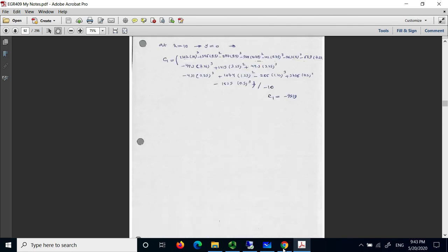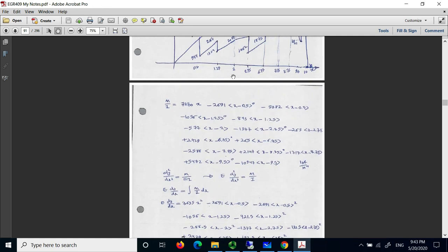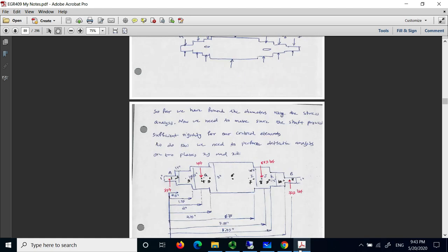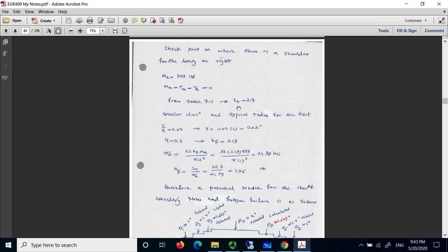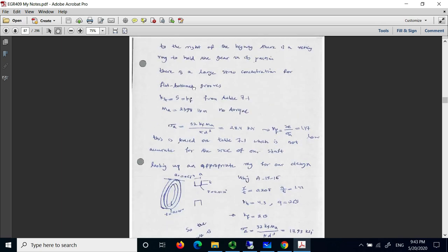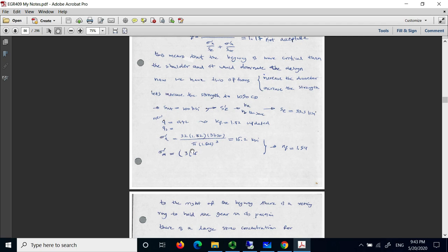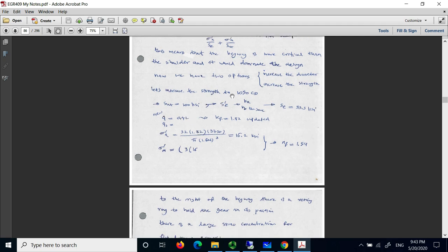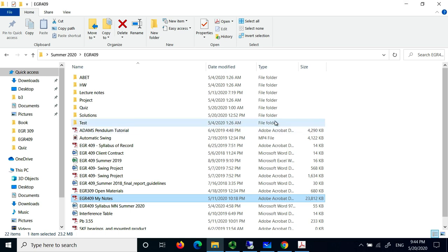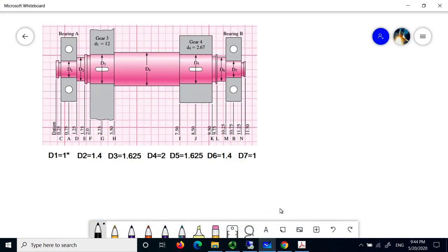This is about the keys. Yeah, alright. So where we changed it was a page before this. Okay, so yeah, 1050. I'm sorry. We had 1020 at the beginning, but we changed it to 1050 because we didn't have enough endurance limit. But as I said, it doesn't matter.